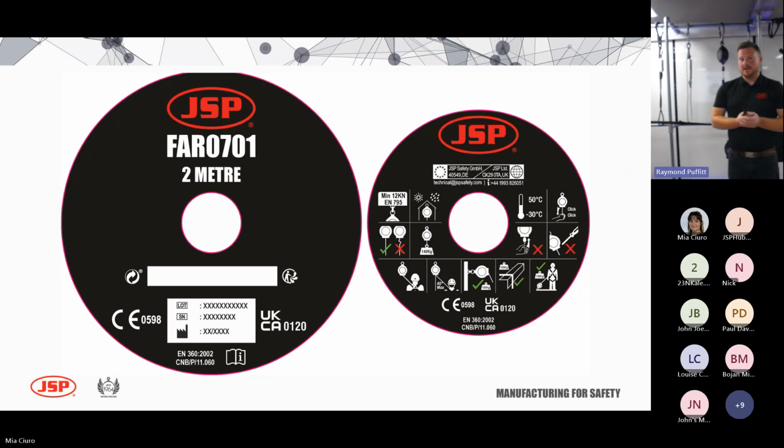The way the product label looks, again, for the specific block you have, it will tell you what the differences are. So all the icons are included. We also have weight limit differences depending if they can be used at sharp edge, horizontal, or foot level. So for this particular block, this is the mini block, which we'll show you in a second. It's 100 kg for horizontal over a sharp edge at fall factor 2. But when you are using it above head height in a vertical use situation, it is 140. Again, all little things to be thinking about when you're using this type of equipment.